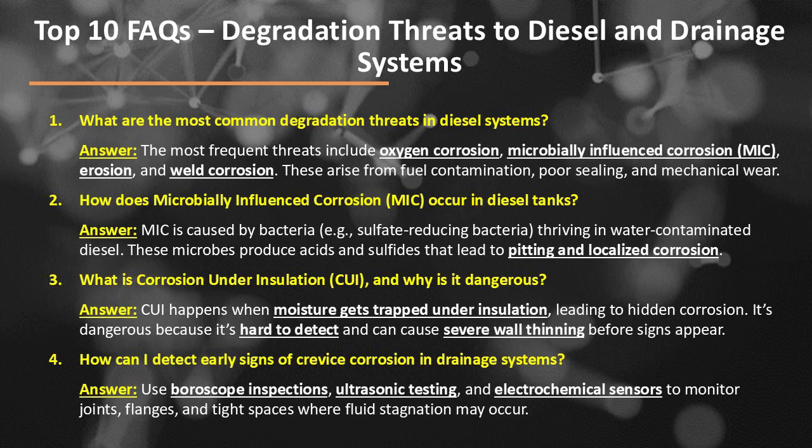Top 10 frequently asked questions in terms of degradation threats to diesel and drainage systems. Question number 1. What are the most common degradation threats in diesel systems? The answer is, the most frequent threats include oxygen corrosion, microbially influenced corrosion or MIC, erosion, and weld corrosion. These arise from fuel contamination, poor sealing, and mechanical wear.